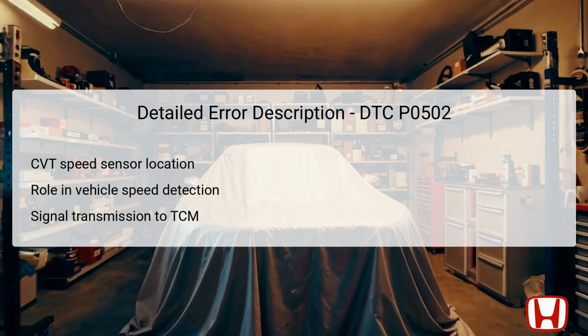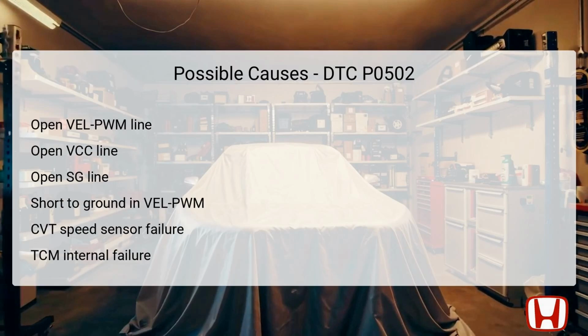A malfunction in this sensor or in the circuit may prevent the correct pulses from reaching the TCM, thereby leading to incorrect speed readings or potential gear shifting issues. This disruption usually triggers the DTC P0502 code, along with visual alerts on the dashboard that indicate a need for immediate attention. Several potential causes can result in the DTC P0502 being triggered.